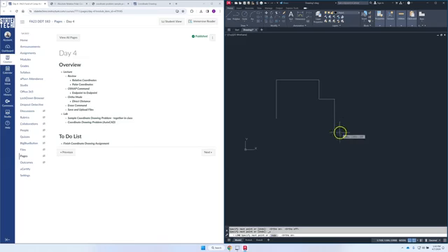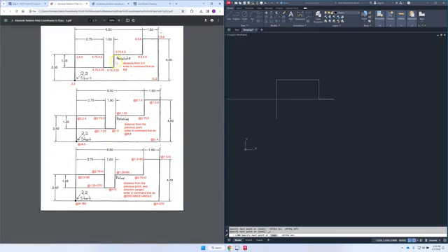Also, if I want to draw the next line on this shape, right here, it looks like it goes up 1.25. With ortho mode, I drag my cursor the direction I want to draw. So if I want to draw up, I'll drag it straight up. And all I have to do is type that distance, 1.25. And it automatically draws that line at 90 degrees. So it's polar, but faster, basically. So that is direct distance. It's what I personally use every single day. It is one of the fastest input methods for square shapes.